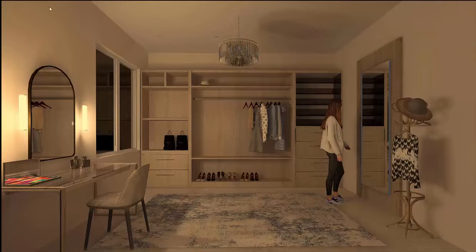One row is here, second row I can place it here, and I can use one of these adjustable downlights and direct it towards here so that I have enough task lighting on the table as well. Okay, so this was about the task lighting layer.